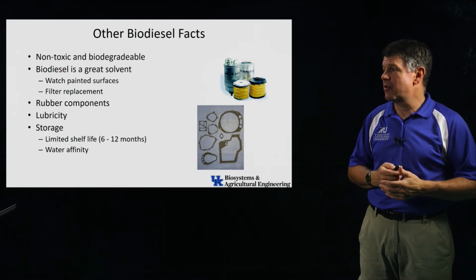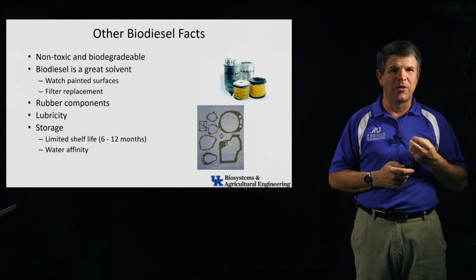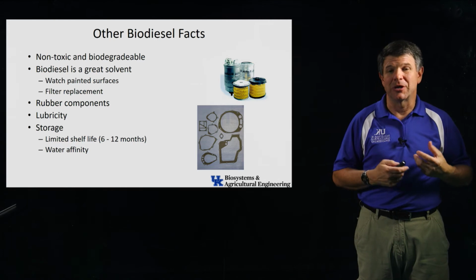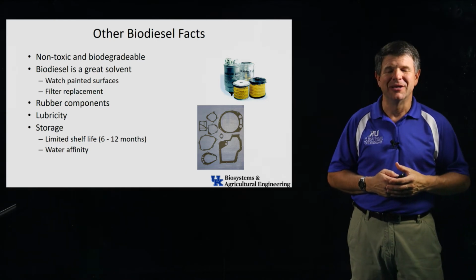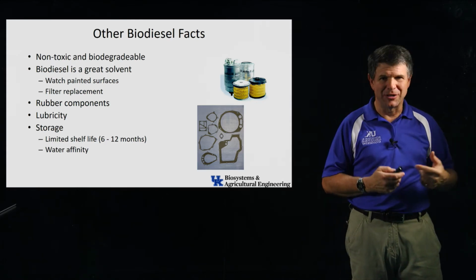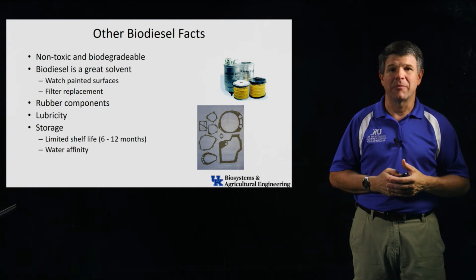And the other thing is, a lot of these fuels, biodiesel and ethanol, they love water. So they will absorb water. So if you get water around the fuel supply, they'll soak it up and pull it in. And that's bad to have water in your fuel. So that reduces your lubricity. It doesn't burn as good. There's not as much energy content. So you really have to think about how you manage your fuel supplies.